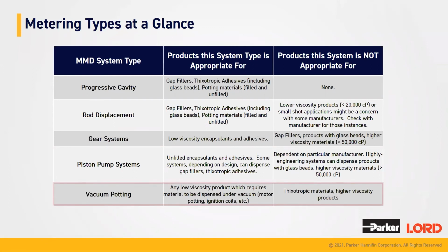And then the vacuum potting is another system that can be used, definitely recommended for moisture sensitive systems and any low viscosity products, but it's not great for thixotropic materials or higher viscosity products.